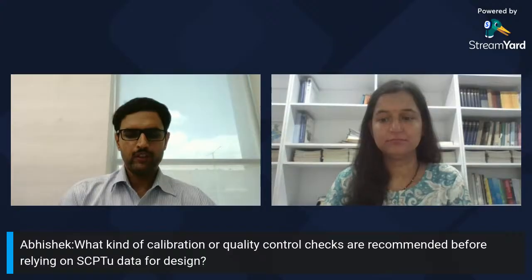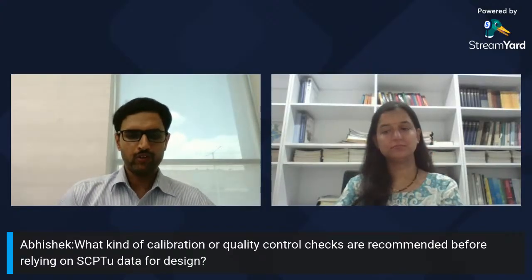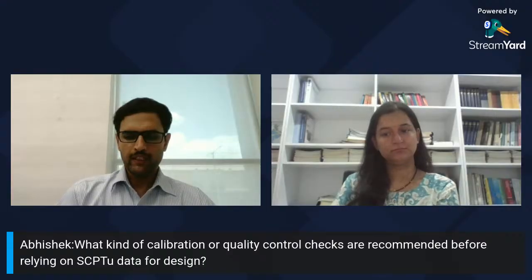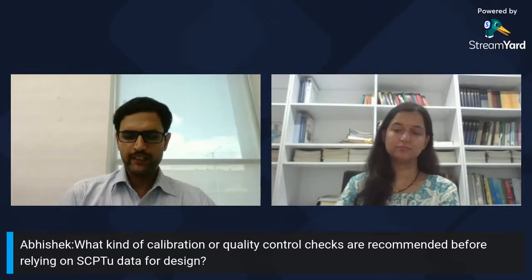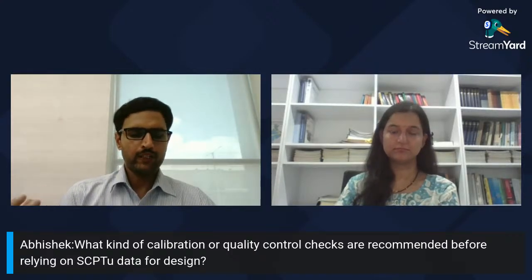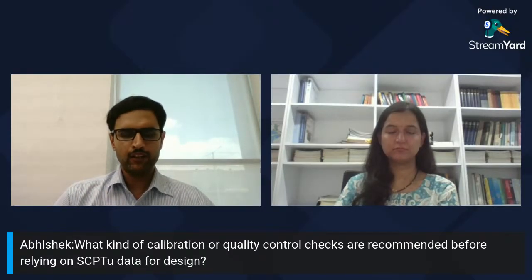In terms of quality control checks for your seismic data, as we saw in the presentation, your seismograms are what's most critical. As you're collecting the seismic data, and when you look at the seismograms, it's important to ensure three main things: the initial silence in your shear wave, then the main shear wave of high amplitude, followed by the tail of the wave.